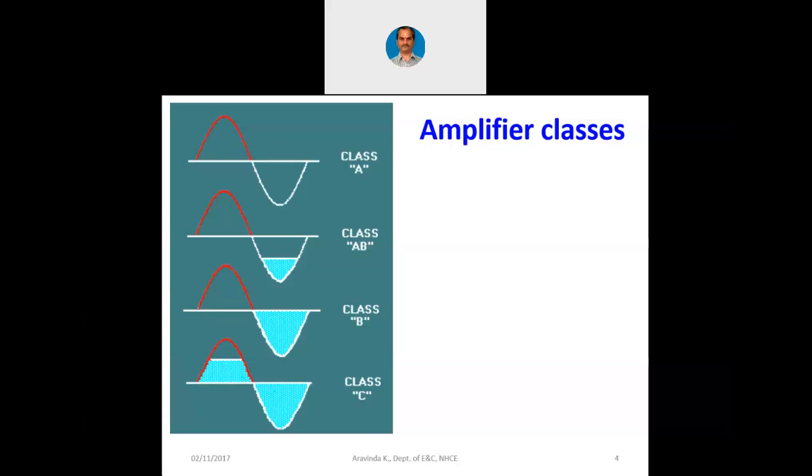Why? Because the carrier is carrying the information signal. The information signal is your voice. The information signal's quality is important, but the carrier's shape is not important. So, in the case of an RF amplifier or a radio amplifier, when the carrier wave signal shape is not actually important, we can use a class C amplifier there.